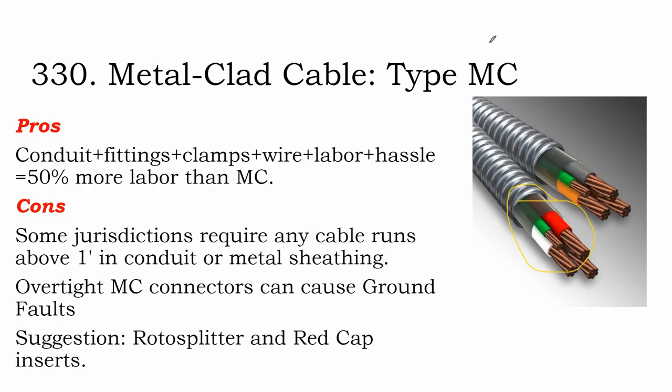Now, the problem with solar cable specifically is that DC solar cable inside of a building needs to be in metal. And so Romex does not work with solar for running cables through the inside of the building. That really led to installers needing smaller than utility scale cable for home projects, for residential, small solar projects, but not having any product availability.